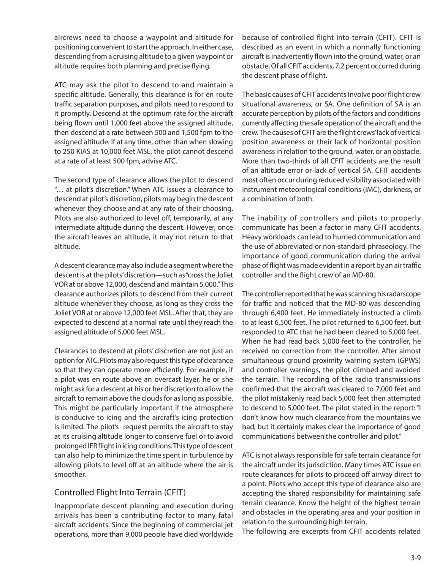The inability of controllers and pilots to properly communicate has been a factor in many CFIT accidents. Heavy workloads can lead to hurried communication and the use of abbreviated or non-standard phraseology. The importance of good communication during the arrival phase of flight was made evident in a report by an air traffic controller in the flight crew of an MD-80. The controller reported that he was scanning his radar scope for traffic and noticed that the MD-80 was descending through 6,400 feet. He immediately instructed a climb to at least 6,500 feet.